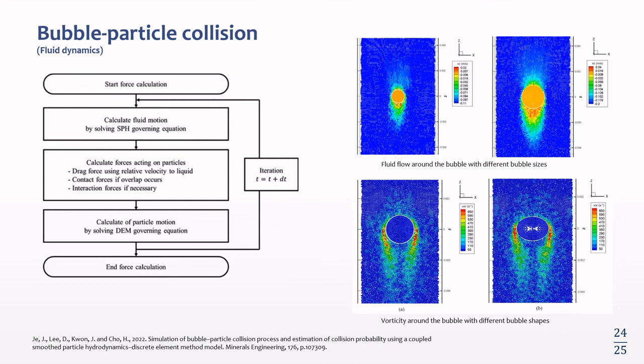As we can see here, it shows us how to simulate the fluid flow around the bubble with different bubble sizes, and also velocity around the bubble with different bubble shapes in the froth flotation environment.